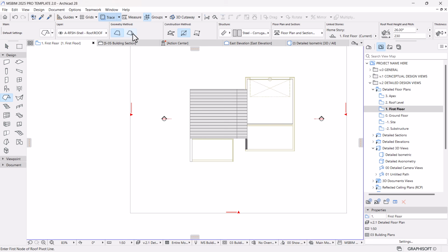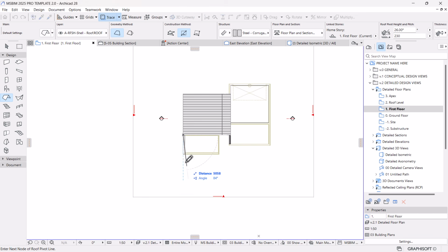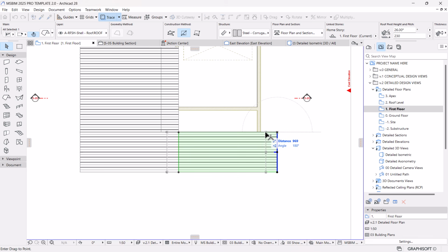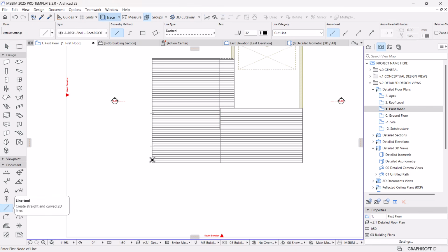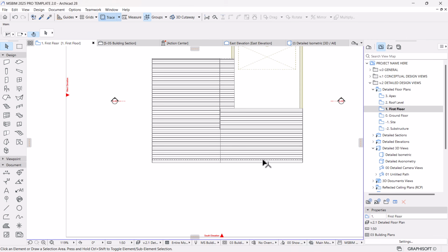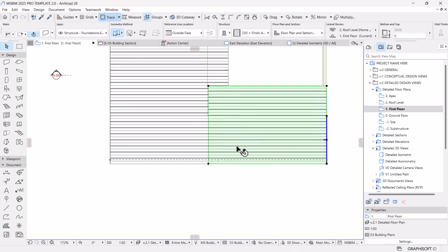When I activate the roof this time around, let's just use the single plane, and it's going to be placed that way, and I guess that will be the center. Control Shift M to mirror copy to the side. I'm going to drag it to there, stretch all the way to there. They need to meet at the center. I have to find the center point for this area, which is there. So this is the center point.